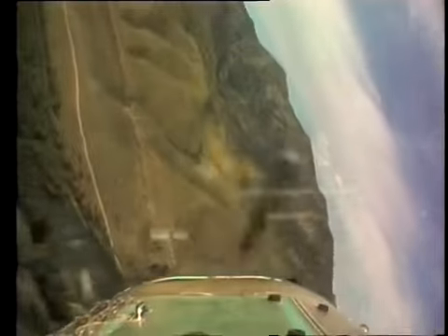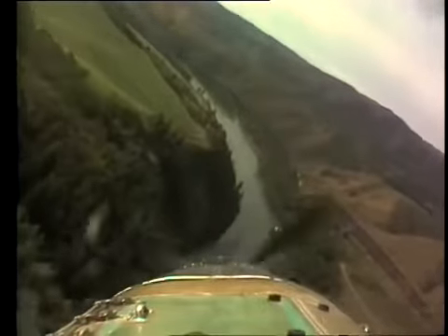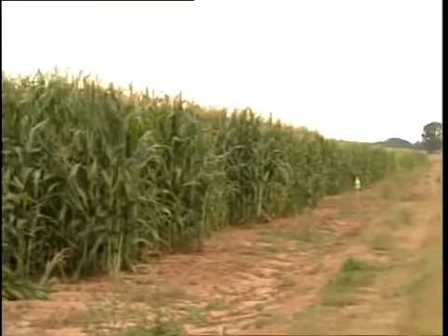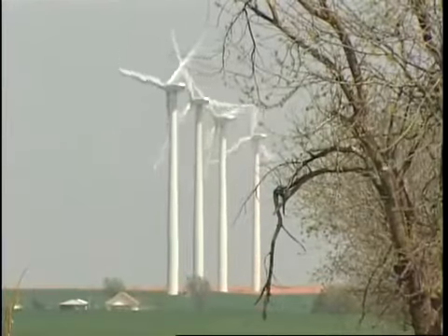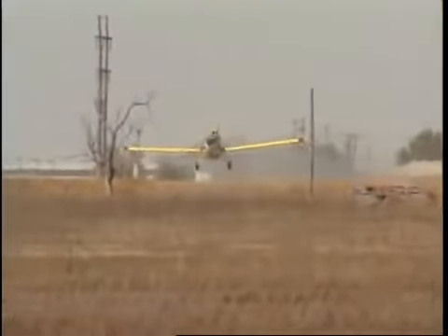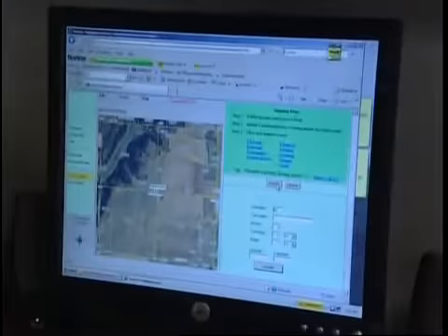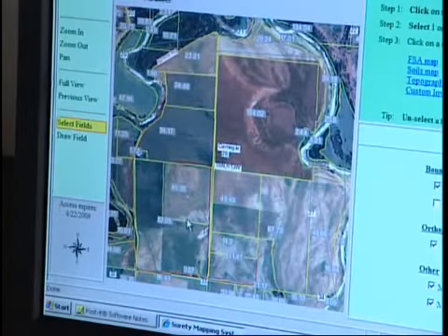The pilot determines if there are any environmental concerns in that particular area, such as water supplies, buildings, pastures, or wildlife habitats. He must also know what crops are being grown in adjacent fields, as well as obstacles he must avoid, such as wind turbines, power lines, and towers. The pilot makes note of all these factors on his work order or field map.